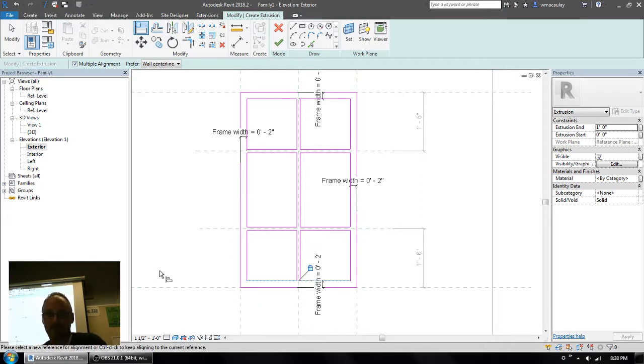There we go. So once you've aligned those 2, find some white space. Now we'll click the one that has a dimension on it, and then we'll click the ones that don't. So I've got 3 sides sorted. I just need to deal with the 4th side. So click in some white space first. Pick the one that has a dimension on it, then pick the one that doesn't. And we're good to go. What happens if we pick in a different order? It would actually still work. As long as they're all together, it's all good. Yeah. Good question.